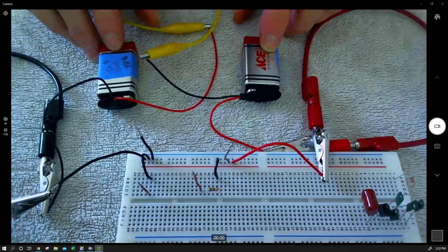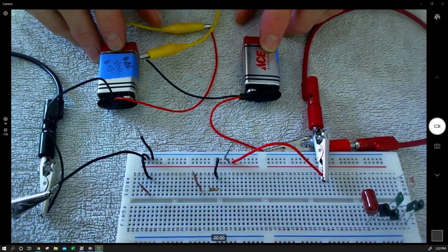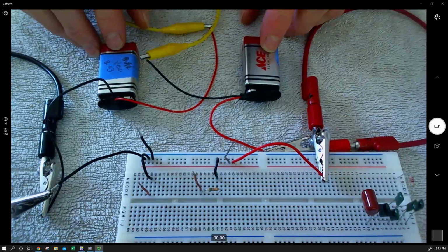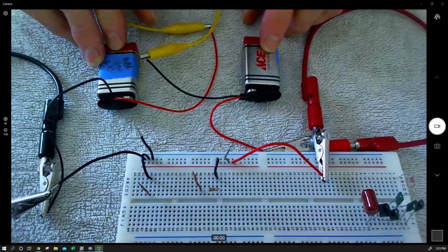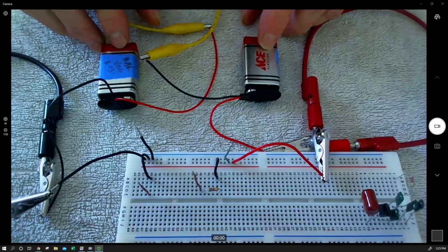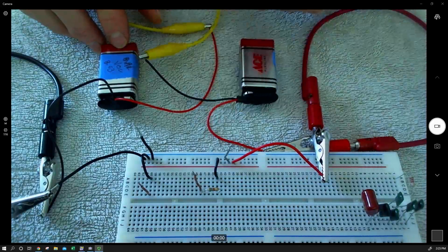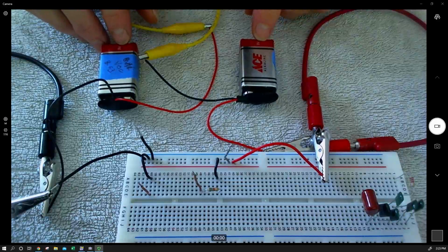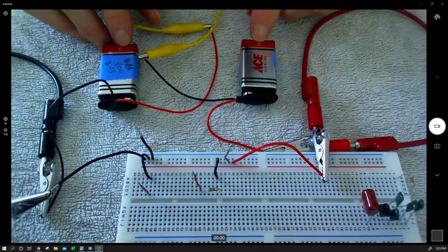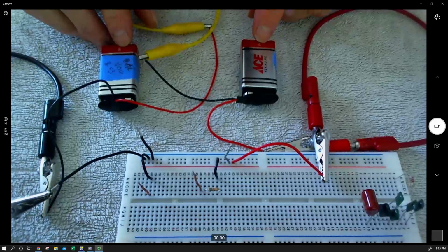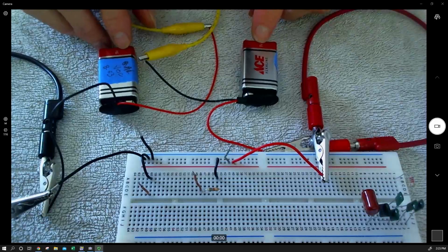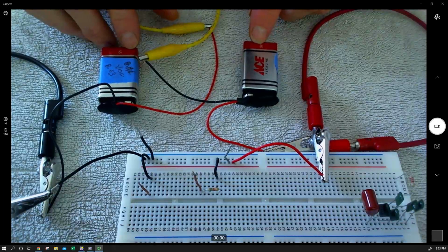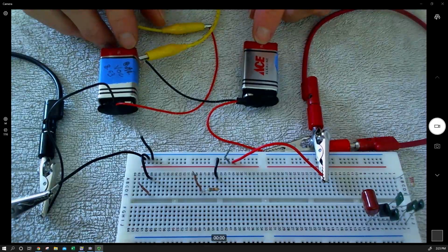And this doesn't just affect batteries. Sometimes small instrument supplies like a USB function generator might have very low current capabilities, and so your predicted current from Ohm's law from your circuit might be much greater than what you actually get if your circuit has a low load compared to the current capability of your device. And in the case of function generators, that will manifest as not as high a voltage as you thought you would get, and that's known as voltage sag.